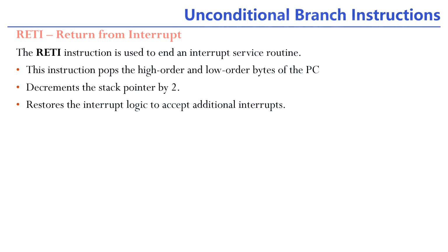As compared to the return instruction, this instruction also retrieves the PC value and decrements the stack pointer by 2, but it also restores the interrupt logic. In the 8051 microcontroller, whenever an interrupt comes, it will disable the remaining interrupts. So to enable further interrupts, it has to restore the interrupt logic additionally. So that is an additional operation of the return from interrupt instruction in the 8051 microcontroller.